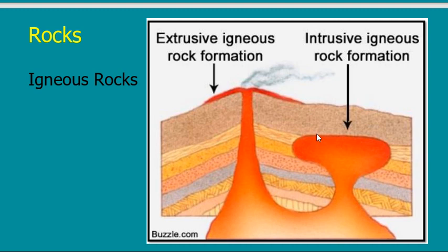I may go maybe 10 meters in igneous rock just to prove that the igneous rock will continue a very big distance. But if it is just a thin layer, 1 or 2 meters, I cannot just take 1 or 2 meters in igneous rock and stop. No, maybe it is followed by very soft sand below or very soft clay.